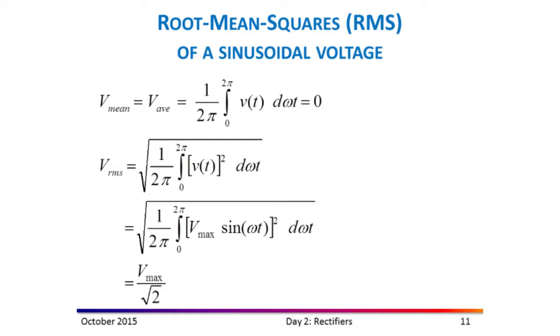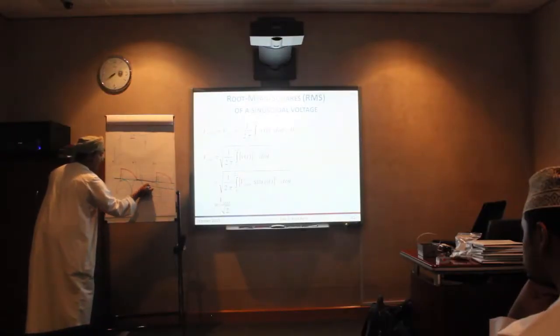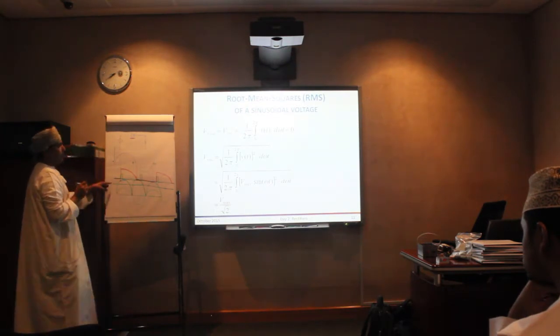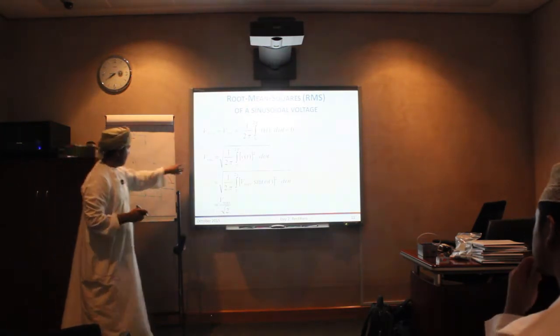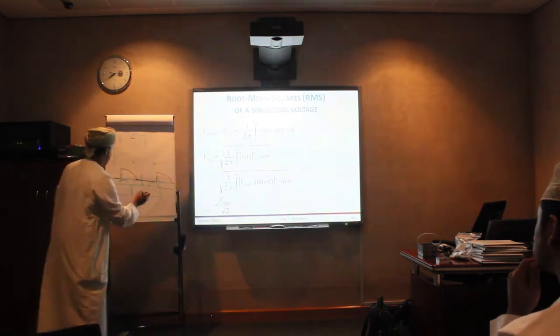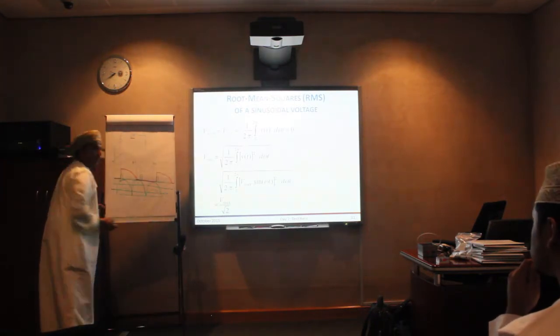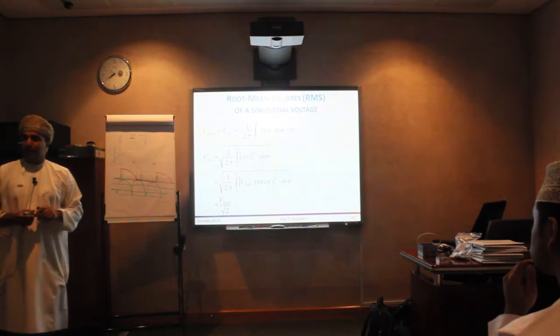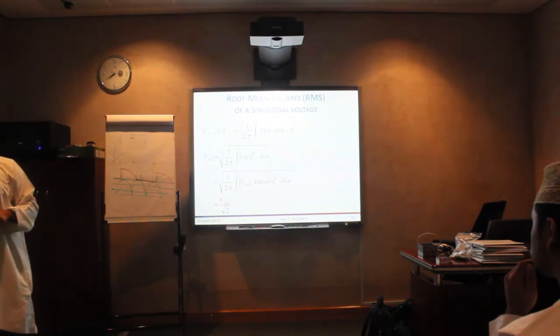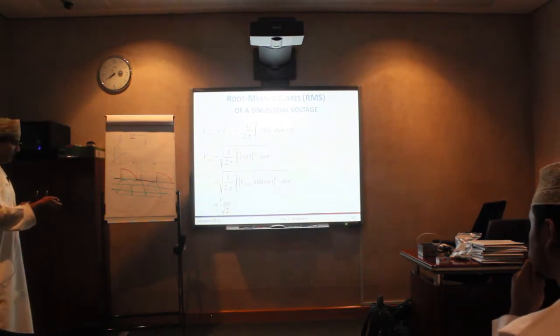And then if I square that one, I will have this, and if I square that part, I will get that. Now, if I try to get the average of this one, definitely I can get that average, right? And then if I put this average under that square root, I will get this value, which is the RMS value, which we normally use in our AC calculations. Okay, this is how we can get those.